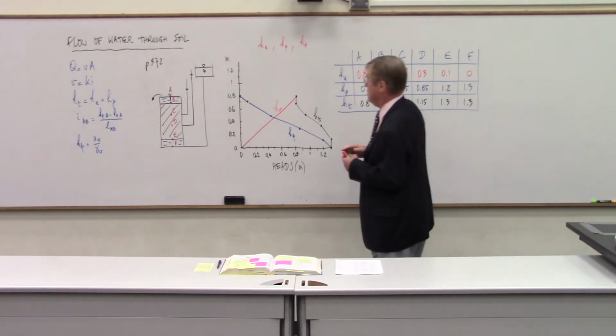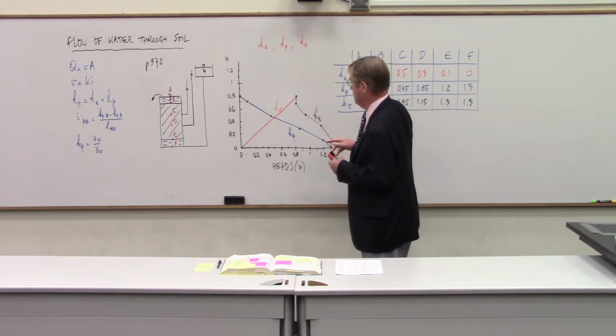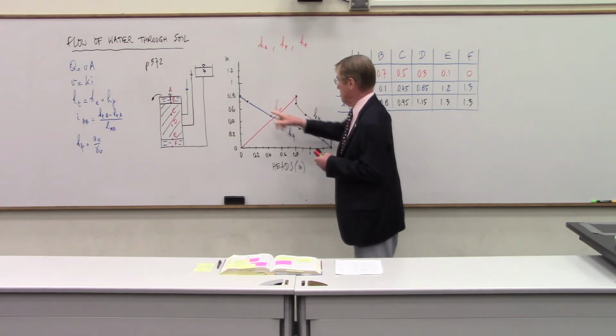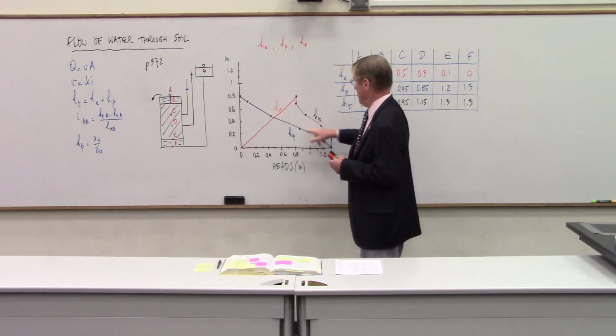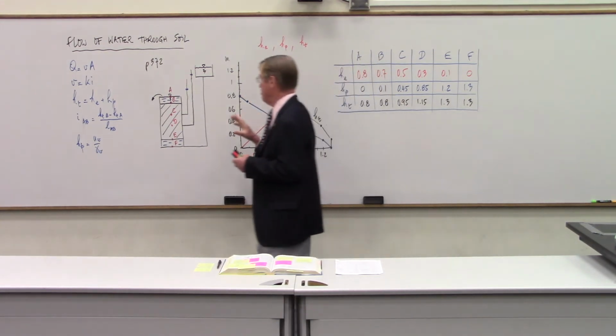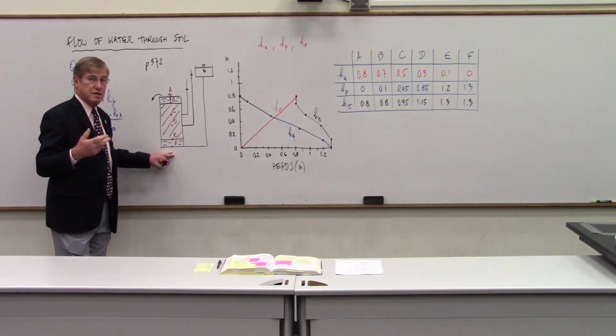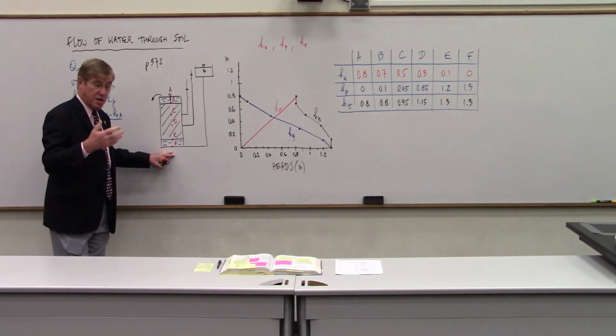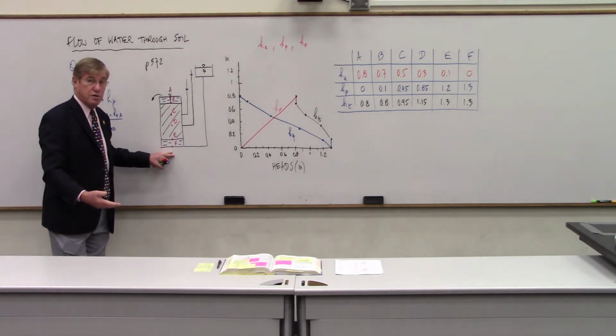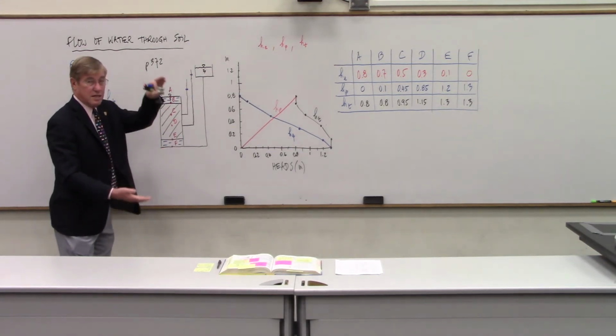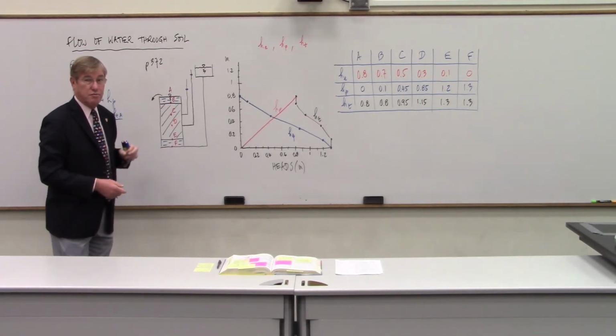And you can see that obviously the pressure is increasing as you go deeper, but the pressure at F, you know, we've seen when we did the effective stress calculation, we had a certain depth below groundwater level, and we said it's that depth times the unit weight of water.